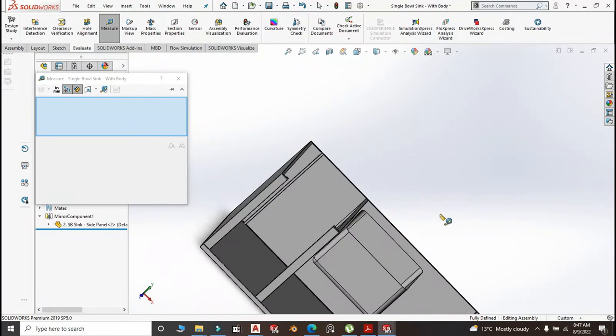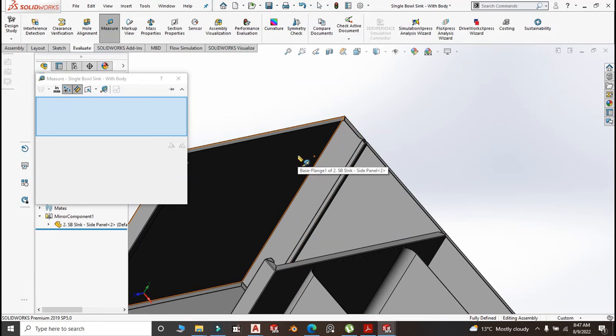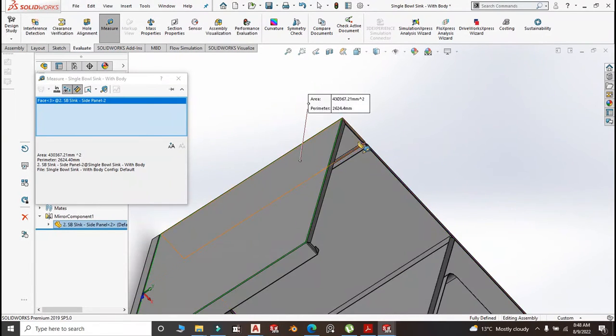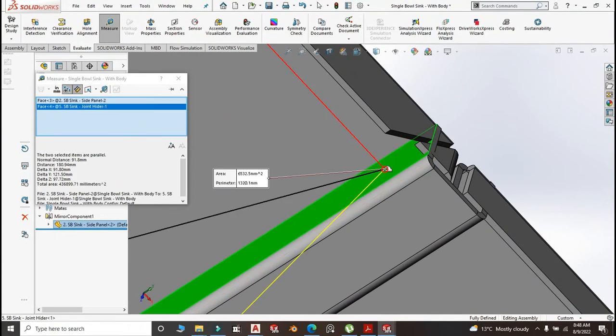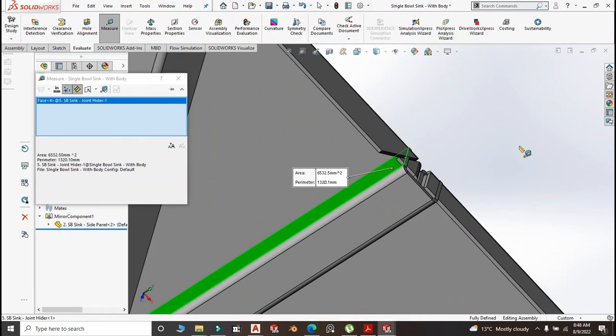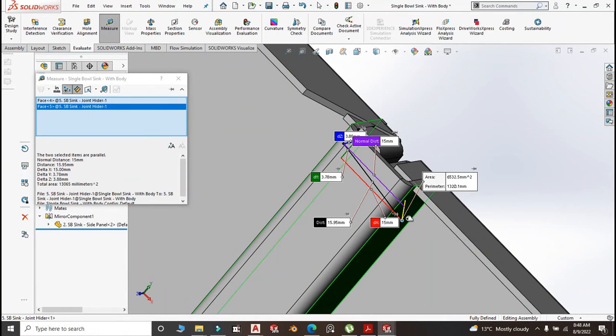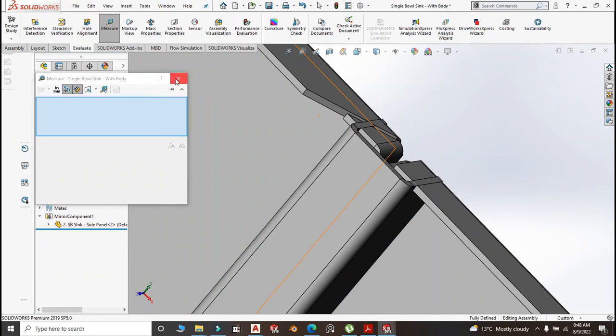Then this panel, this undershelf, mid shelf here, we are going to notch it. So measure from here to here. That should be around 91, and the gap is around 15mm or 20. You don't want to notch it big. 15 notch is 15mm. So yes,